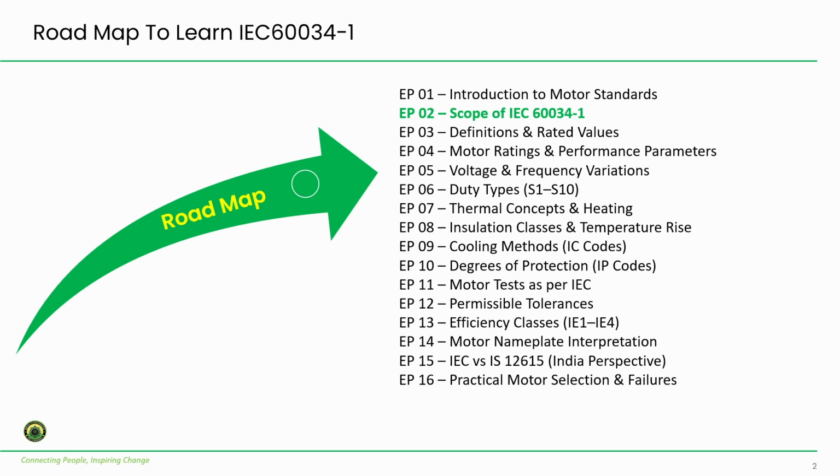Then duty types, thermal concepts and heating, insulation classes and temperature rise, cooling methods, different degrees of protection, motor tests as per IEC, permissible tolerances, efficiency classes, motor nameplate interpretation, IEC versus IS, practical motor selection and failures. So step by step we are going to learn all these things. Let us start with our second episode, the scope of IEC 60034-1.